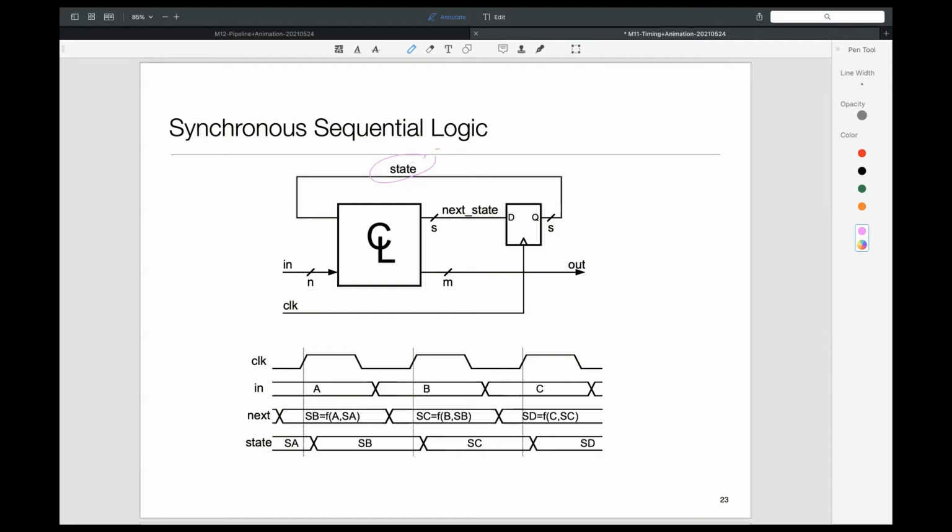One thing to be very careful about is that usually it's positive edge, but just remember, if I have a circuit like this, that means the active edge is the downgoing one. If you are not careful when looking at a circuit, you may get it all wrong. So make sure you understand which clock edge the state register is changing at.